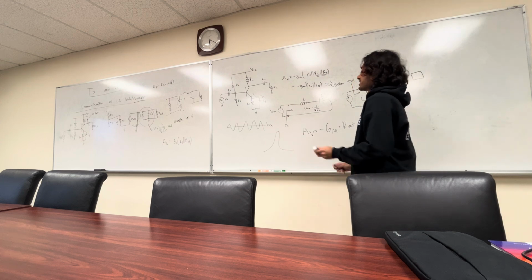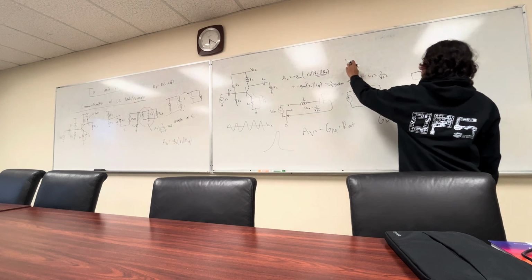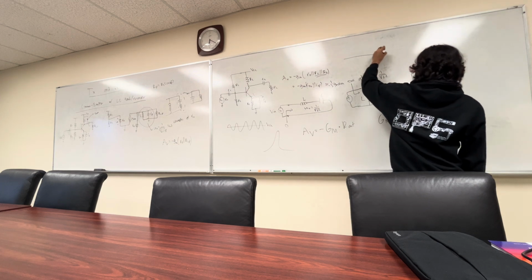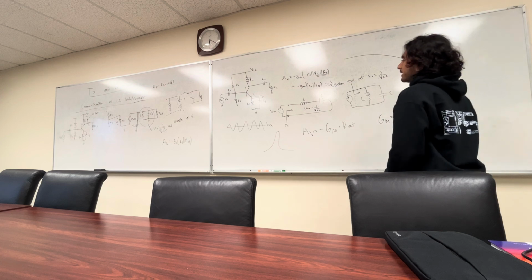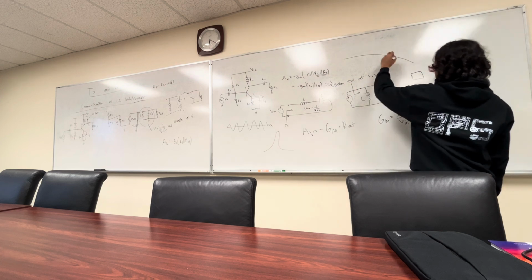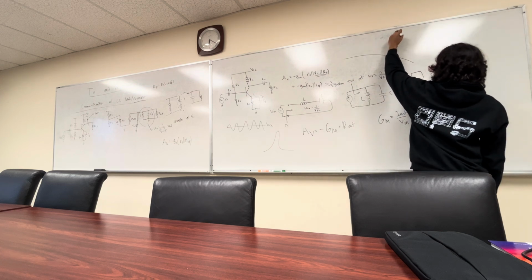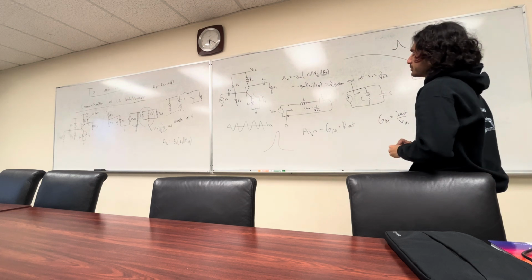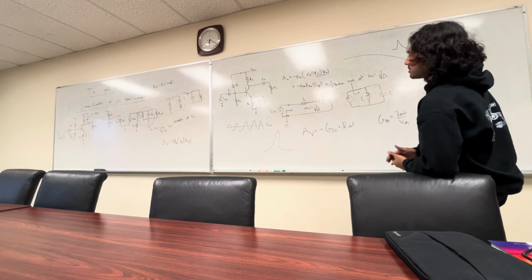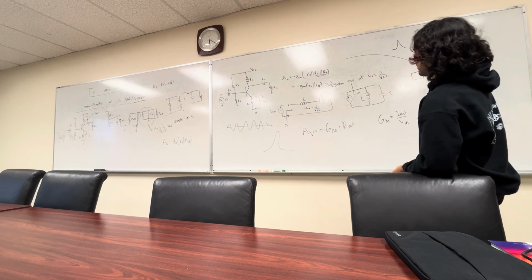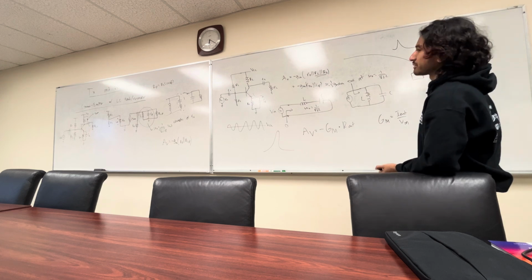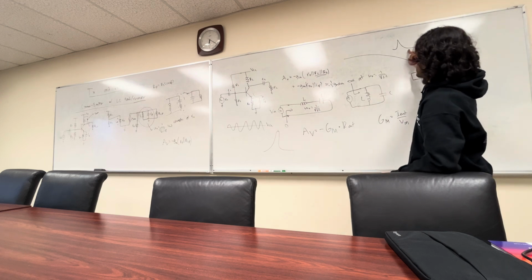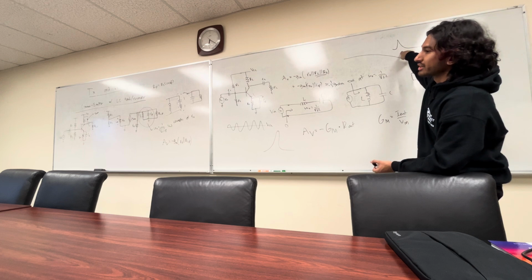When we talk about a transistor, right, you have your FT. So at some point you're going to start to see your gain start to roll off, and you can't just have your gain look something like that. When we want to make things roll off sooner, for your FT, you add more capacitance, which shrinks it down. If you want a characteristic like this, your transistor does not naturally provide this.